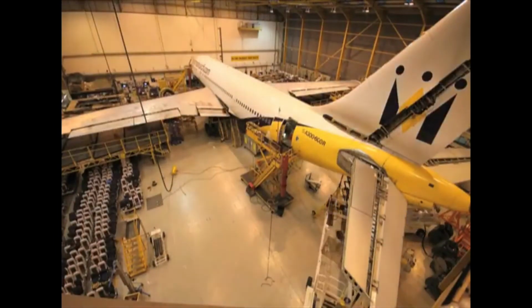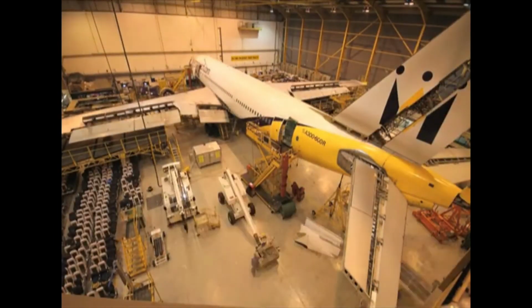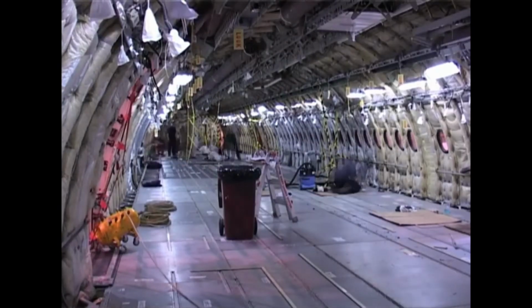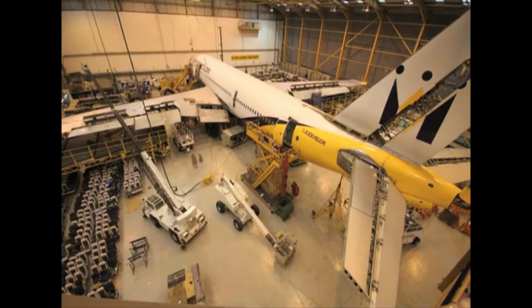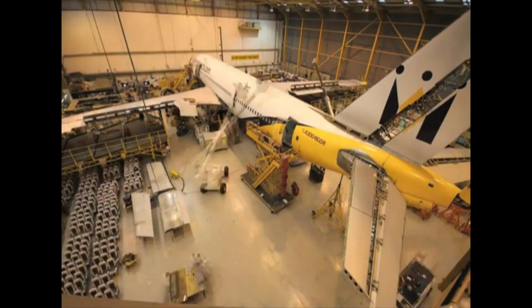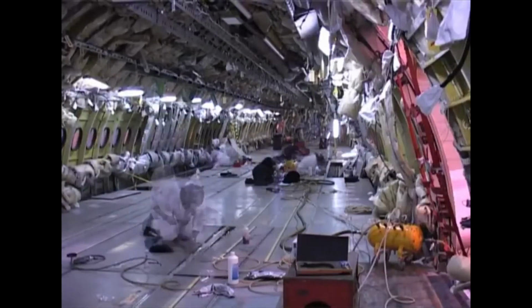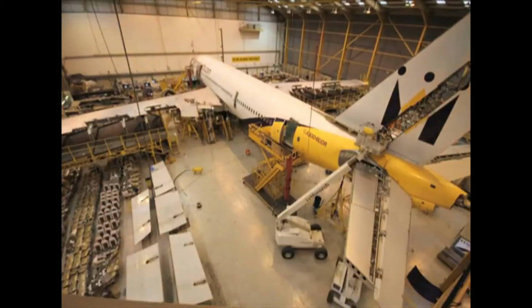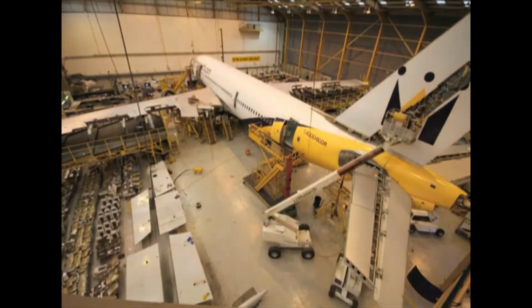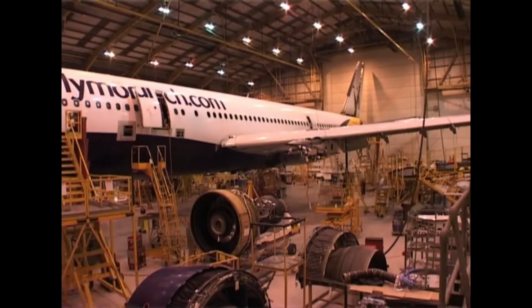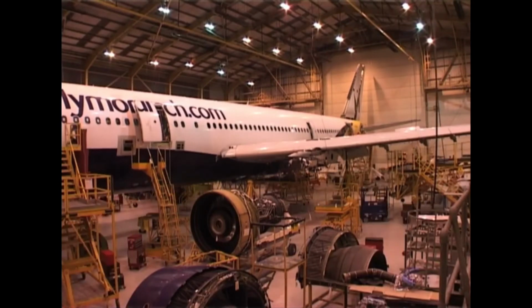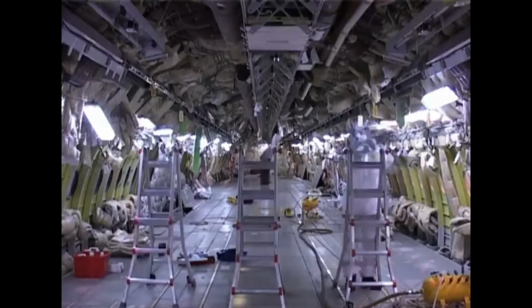An inspection of the damage and an accurate estimate of the type of repair required are the most important steps in repairing structural damage. The inspection includes an estimate of the best type and shape of repair patch to use, the type, size, and number of rivets needed, and the strength, thickness, and kind of material required to make the repaired member no heavier, or only slightly heavier, and just as strong as the original.